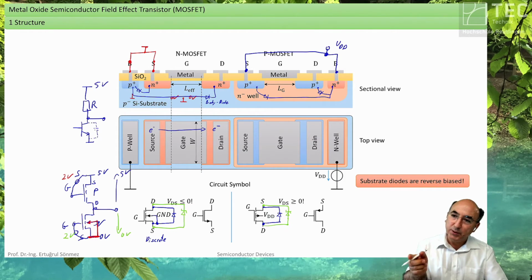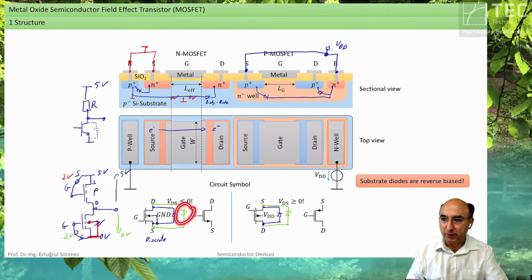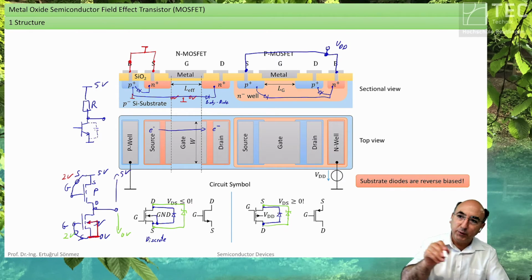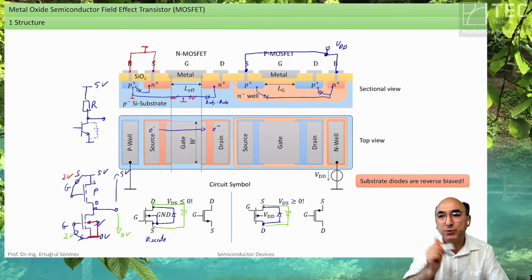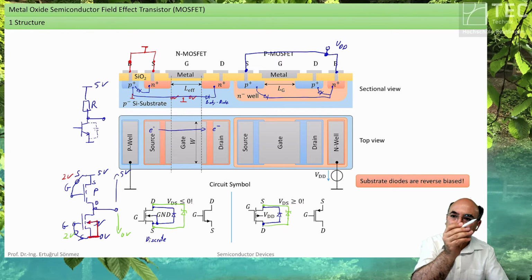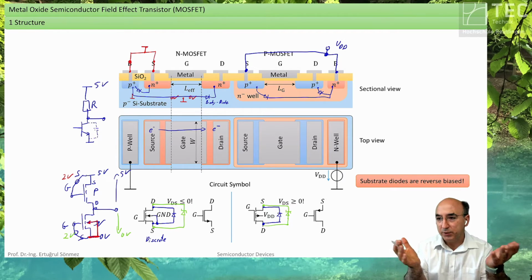Cheap applications, they use a fast silicon bipolar PN diode. A little bit more expensive applications, they use silicon carbide Schottky diodes. But silicon carbide Schottky diodes, they have a higher voltage to have a certain current level. But silicon carbide Schottky diodes, they don't have the diffusion charge. Therefore, it doesn't mind that you have an additional voltage needed for the forward bias of the diode. Because if you reverse bias the diode, you don't have to deploy all the diffusion charges injected into the diode because there is none. It's Schottky.